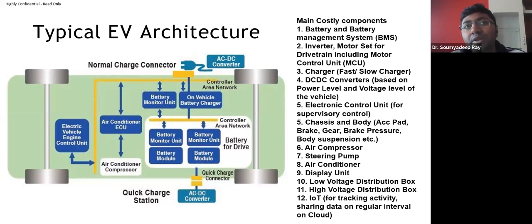There are some typical advantages of permanent magnet motors in an electric vehicle powertrain, namely space and maintenance. So you need the inverter unit, and you need to define the control flow of the inverter, how it is operated. You need to control the duty cycle of the inverter in order to set the motor speed.